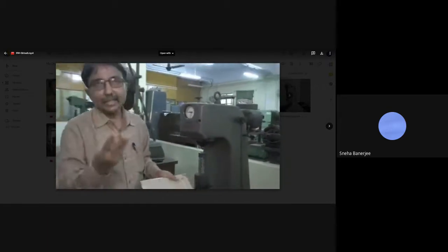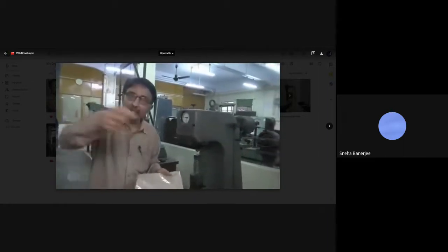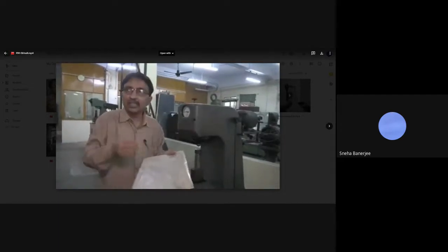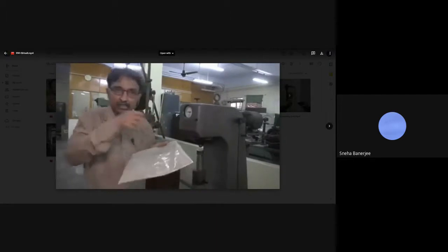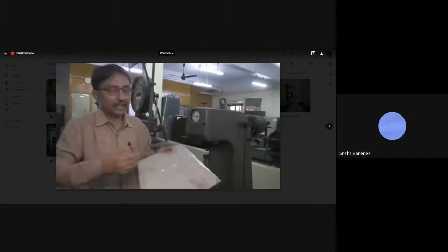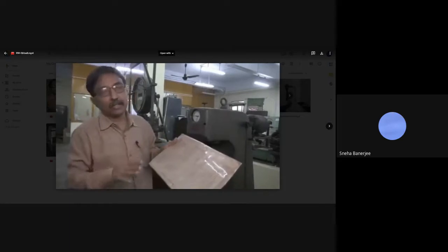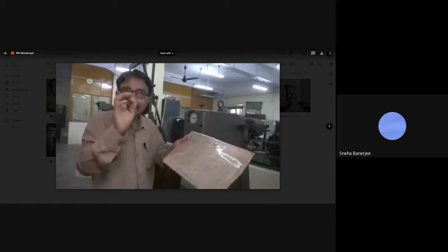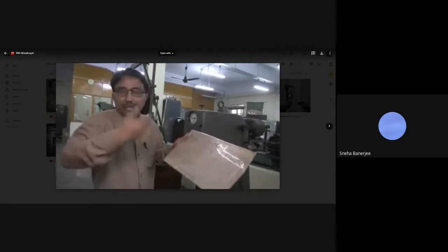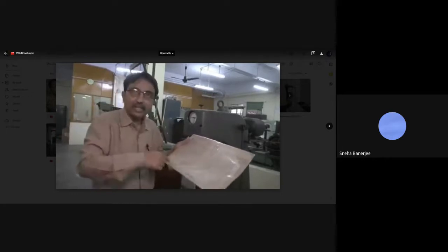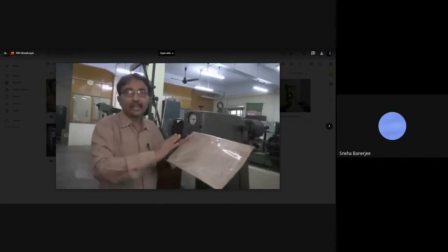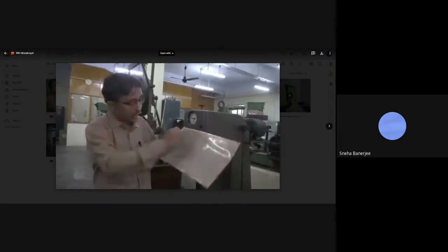What we will do now is the test here, and we will take 2-3 different readings on the same material at 2-3 different positions. Then, using an optical microscope, we will find out the diameter of those impressions, take an average, and use this particular chart to find out the actual Brinell hardness number. Once we get the average diameter from readings in different directions, that average diameter is to be put against the value of Brinell hardness number, and we can find out the Brinell hardness.